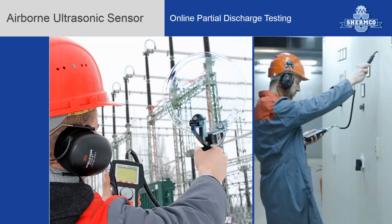Now, another type is the parabolic dish, which is used to extend the distance or the range of the ultrasonic microphone. It's very common to see these parabolic dishes used in the outside plant area. For instance, you may see a technician in a substation pointing these up toward the bushings on the breakers and on the transformers. Again, this is a listening-based technique.